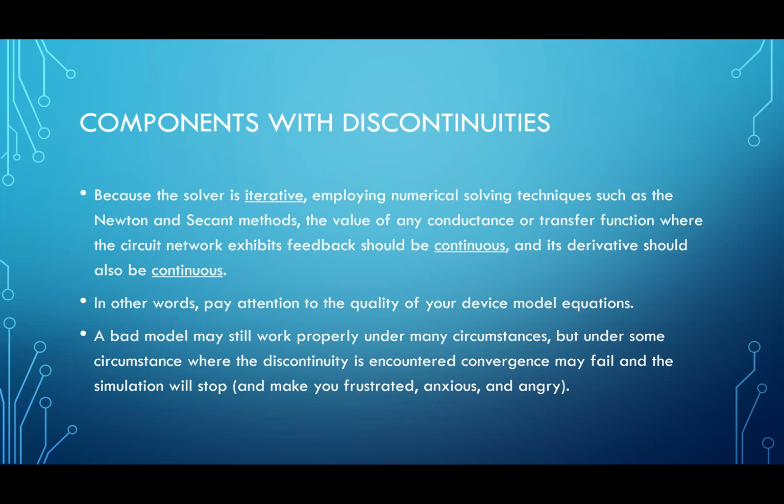So you do have to be careful when you select circuit models, or when you build them, to make sure that the model is a good model. This is true of any circuit simulator. The simulator is only as good as the models that you give it. I mean, some simulators are better than other simulators, of course. Namely, there is a handful of models that most simulators will ever be exposed to, things like BJT models and MOSFET models. And simulators have to be massaged by their creators to be good at solving circuits that have those components. But beyond that, if you give a simulator a bad model that has discontinuities and very strongly nonlinear functions, then you can end up with simulations that don't work.